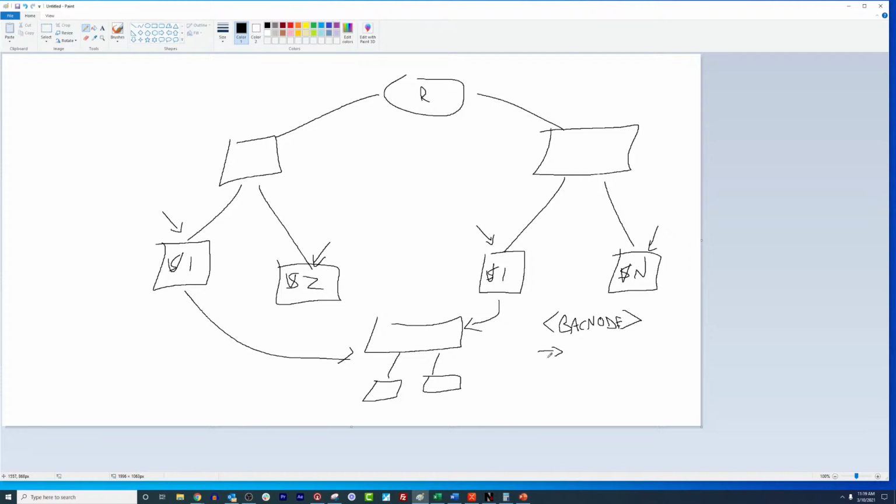So you only need the BBMD and BDTs for Who-Is/I-Am and Who-Has/I-Have. Who-Is/I-Am is device discovery, Who-Has/I-Have is object discovery. Once you have done that, and you've built out your BACnet nodes and the object nodes associated with those nodes, then you are not going to need the BBMD anymore.